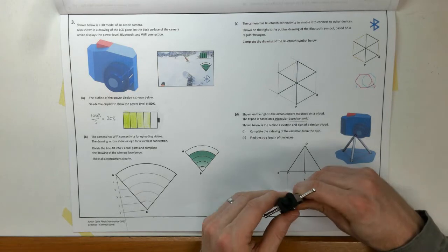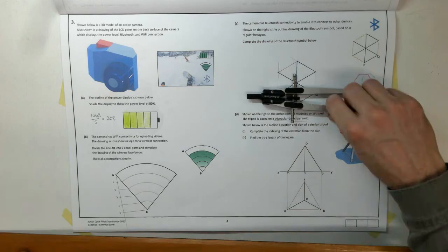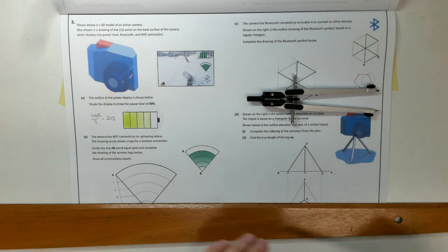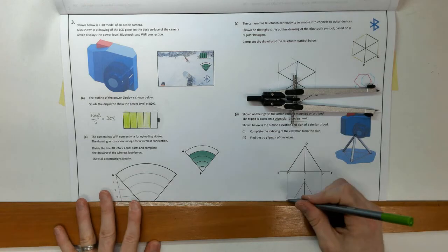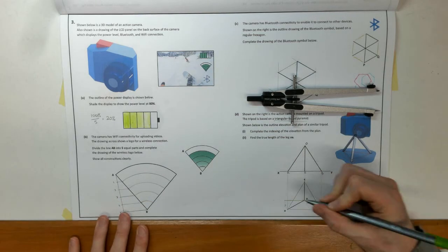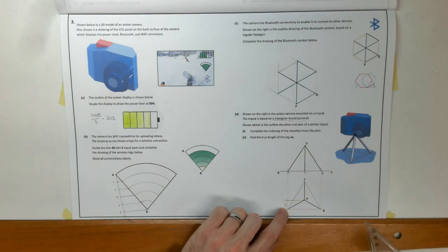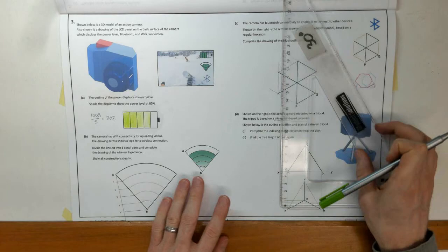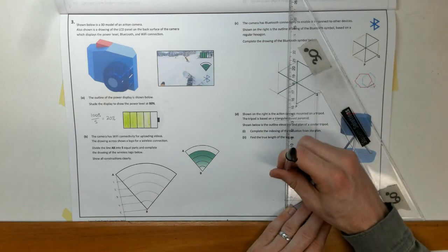So A to O, let's rotate that there. And I'll use colour here to highlight this also. Okay, so I've rotated that there. Now, the height of A hasn't changed, so it's still going to be on the XY line. So project that up.